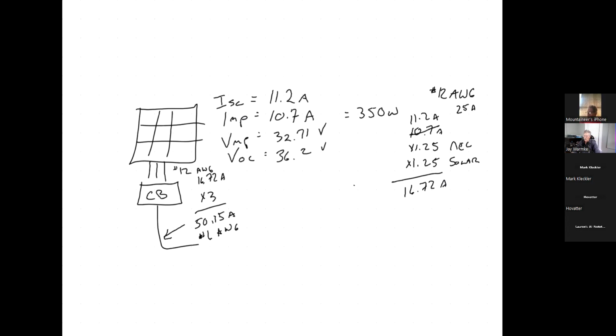All right, so now I'm going to confuse everybody because we want worst case scenario times 1.25 times 1.25 equals 17.5. Okay, so that's now 17.5 amps. Still fine, but it's now 17.5, not 16. And 17.5 times 3 is going to give us 52.5 amps. Okay, so we're still good. 52.5 amps. All right, I worried that it might get over 55, which would mean that we couldn't use 6 gauge.